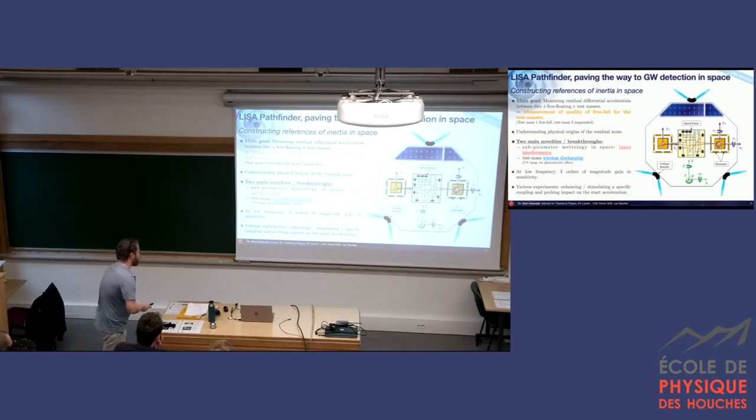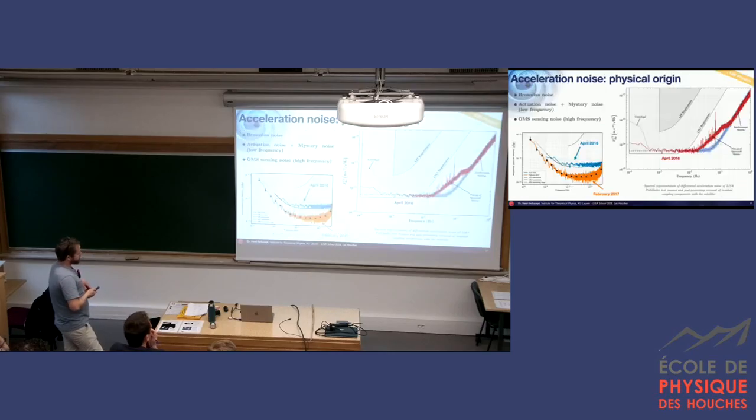So as I said, we were also shaking the spacecraft in all directions to see what was the coupling to the test mass and the stiffness or cross coupling between the channels. And there was a lot of experiment involved. So here are the results. The acceleration noise, so that's not the end result. I put this one because this was interesting, so you can have a glance of what the noise hunting was. You see the noise progressively getting down with the investigations we made.